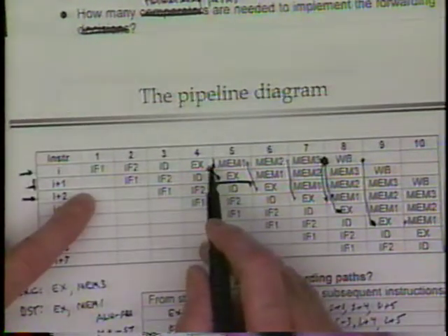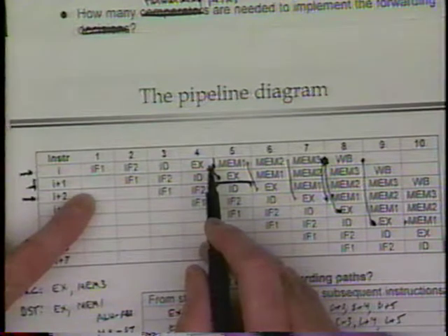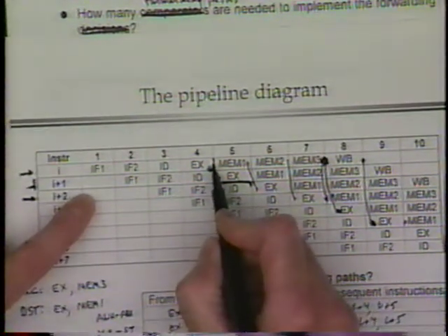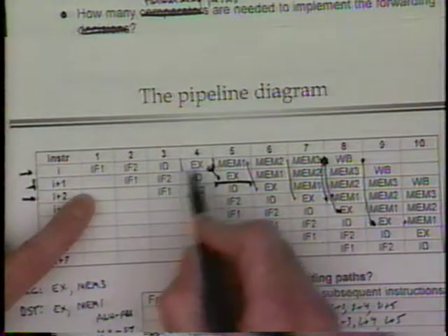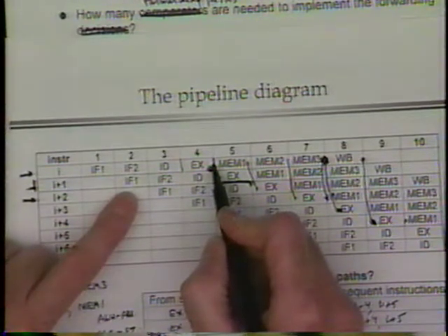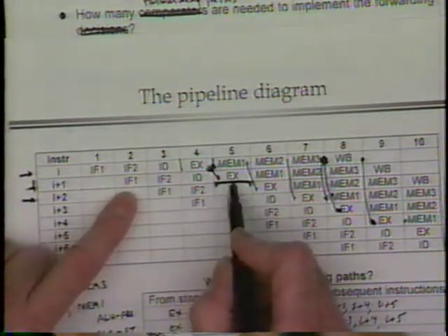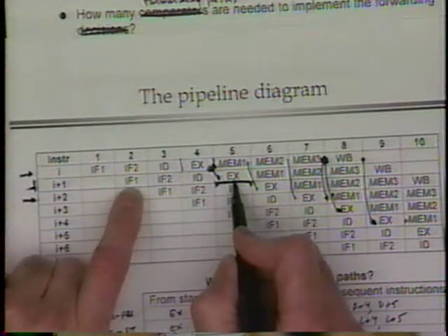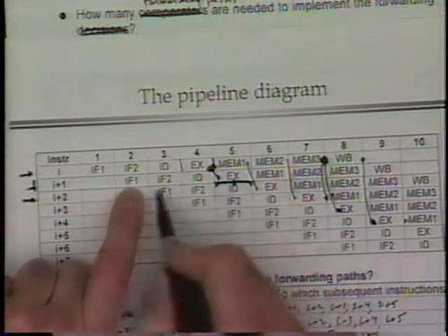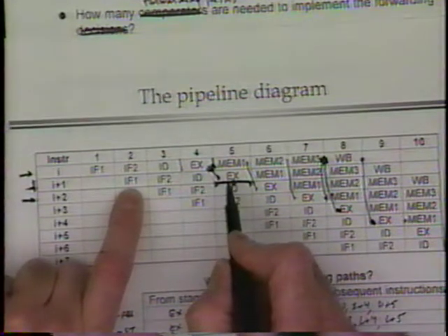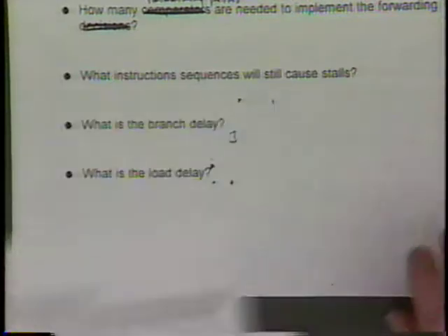The definition of the pipeline said that the branch condition is available at the end of execute. The branch target was available at the end of ID. So if we pick the later of the two, then we know at the end of execute we could certainly begin to fetch the proper next instruction. So in cycle 5 in this example, we could do that. Normally, we would have fetched the next instruction beginning at cycle 2, so there's a 3-cycle penalty. Is that the part you wanted me to repeat? Okay.